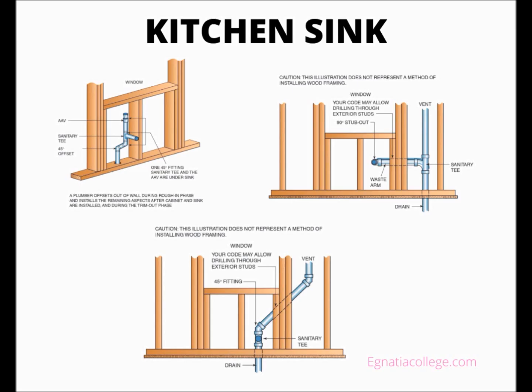Some codes allow 60% of a load-bearing wall to be drilled if it is doubled with another wall stud. However, no more than 2 doubled load-bearing studs can be drilled consecutively. 60% of 3½ inches is 2.1 inches, 2 1/16 inches, which allows a 1½ inches pipe to be installed. A typical window frame is supported by at least 2 wall studs, and some inspectors require that additional studs be installed before drilling the window framing studs.